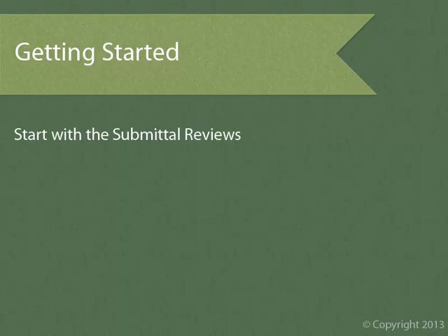Now I want to reiterate that we're coordinating the work of the various subcontractors, not the details in the contract drawings. This is a very common source of confusion, so I want to be sure that this key definition is clearly and boldly conveyed. Contract drawings are diagrammatic in nature, which is fine because each individual sub has their own ways of doing things, their own preferred means and methods, and this is exactly why they always provide us with shop drawings, product data, manufacturer's details, etc. That's one of the primary reasons that the submittal process exists.